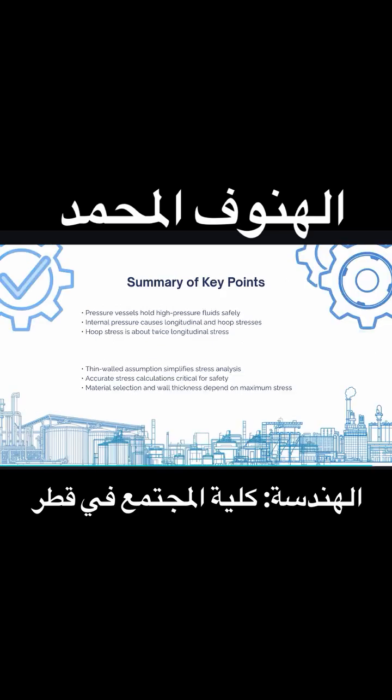In summary: pressure vessels hold high-pressure fluid safely. Internal pressure causes longitudinal and hoop stress. Hoop stress is about twice longitudinal stress. Thin-wall assumptions simplify stress analysis. Accurate stress calculation is critical for safety. Material selection and wall thickness depend on maximum stress.